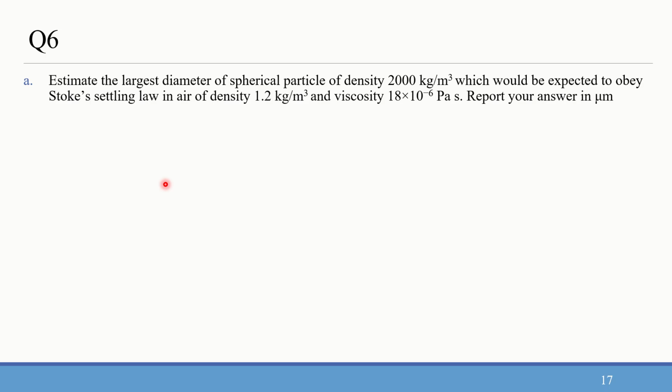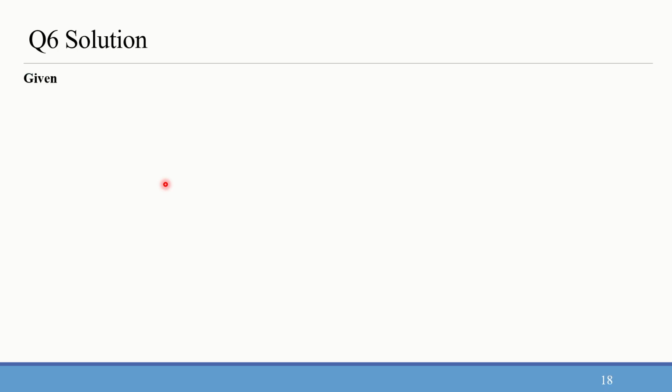So again, to maintain that, the Reynolds number Re is equal to rho v dP by mu. If mu is very low, the Reynolds number increases. Here density is also low. So density is low, mu is very low, so it is somewhat low value. What we can adjust is the diameter of the particle. So on that basis it was asked.